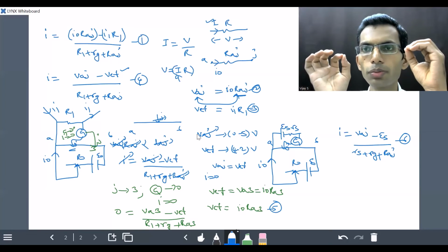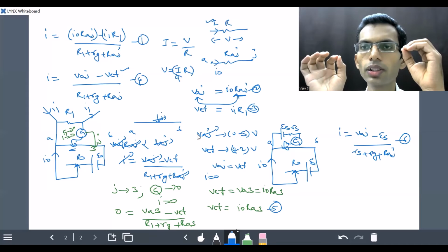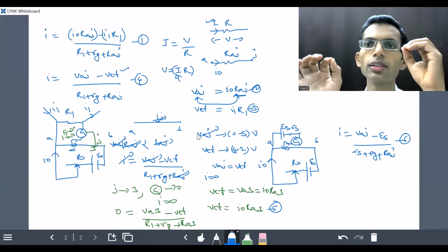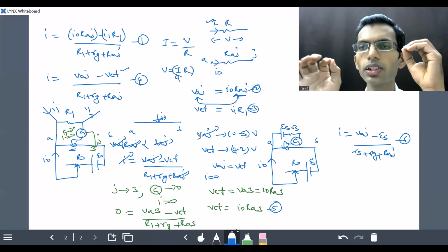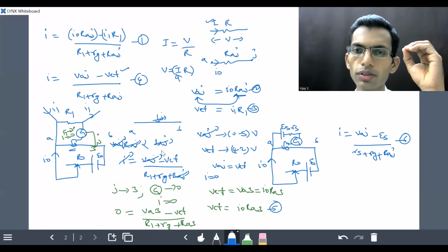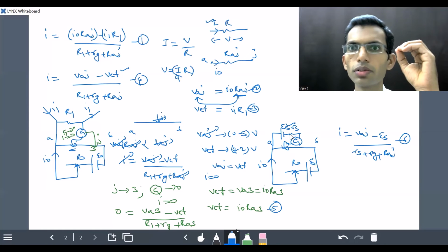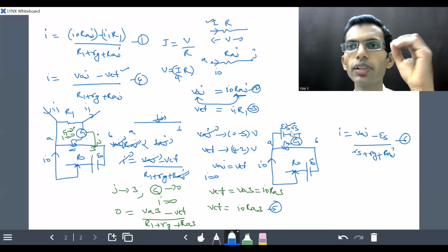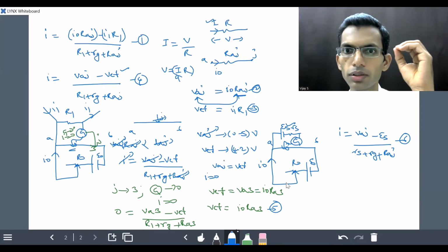So at that particular position, the zero deflection condition, our objective in this case, the EMF of the standard cell, becomes equal to the potential difference between the junction and moving contact position. Here, the interesting thing is ES is known, so we have to note that the standard cell EMF is given.